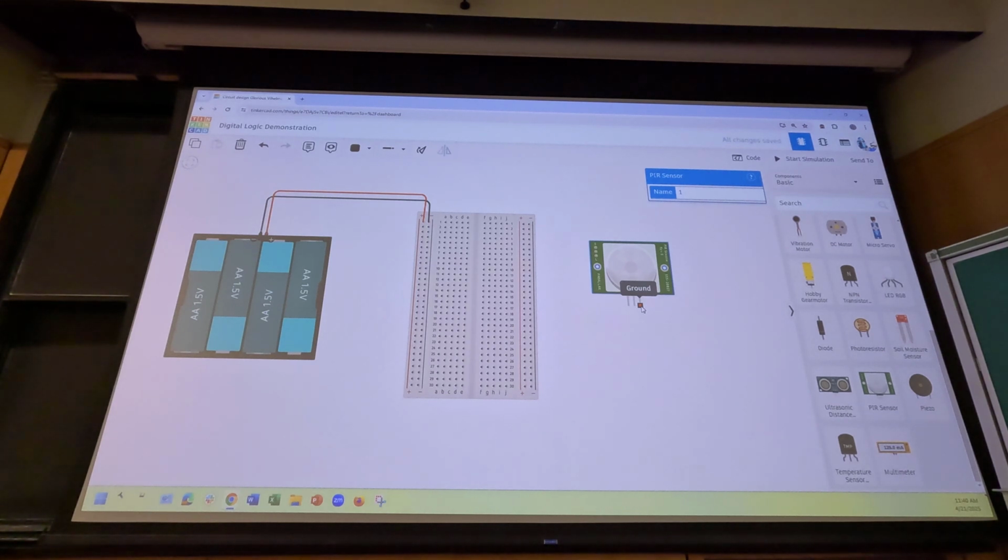So inside that little plastic dome are 2 infrared sensitive photodetectors. So they detect a differential change between the 2 of them. So it's not just a single detector measuring absolute infrared light. It's looking for something kind of moving across the field of view. We're not going to get too much more into the internals of how they work. But they have this plastic dome on top because they're designed to have a very wide field of view.